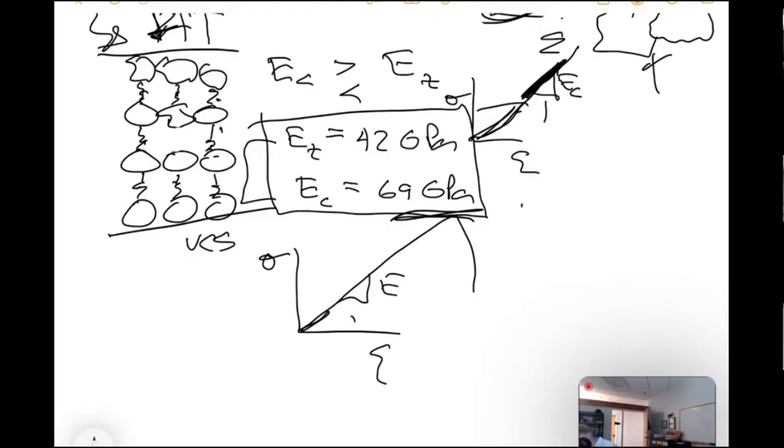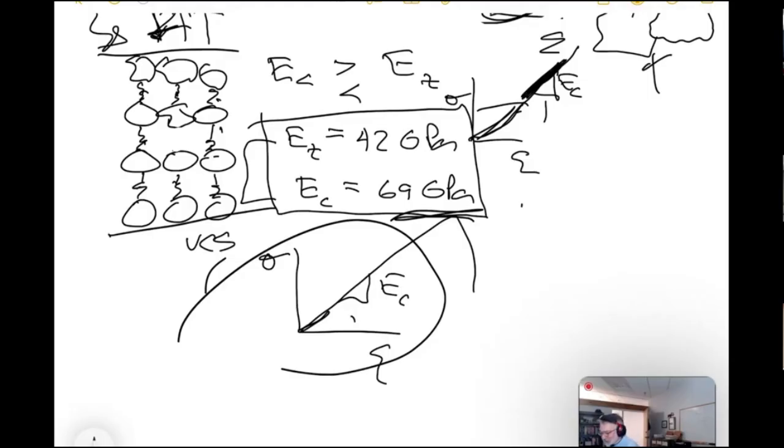But actually, if you look at tensile tests on that same thing, you will find that the modulus will be less. Okay? Which means that even simple granite is not behaving like a linear elastic isotropic body, because its modulus is different depending on how it's loaded.